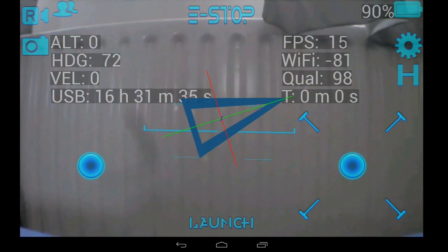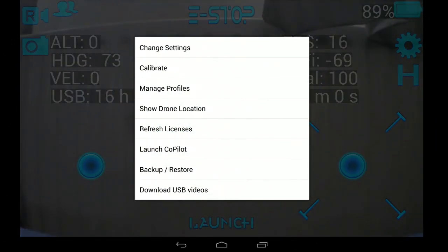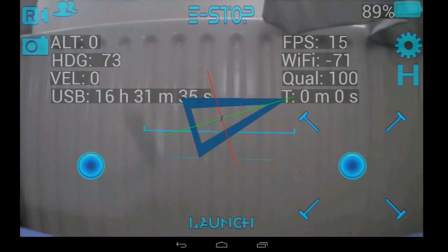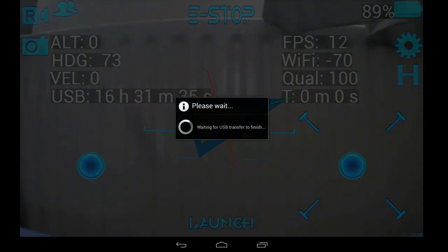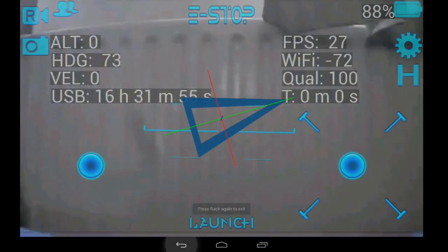Right. When you start recording, the drone is still doing conversion, so you basically want to wait for the drone to finish its conversion. You see this brief flash of the LEDs on the drone as it's finishing, but it's not fully finished at that point. So if you then try and download USBs, it won't necessarily have transferred, but here I've selected the dialog to show you USB activity. If you don't select it, then it will do it in the background. But there it was downloading.